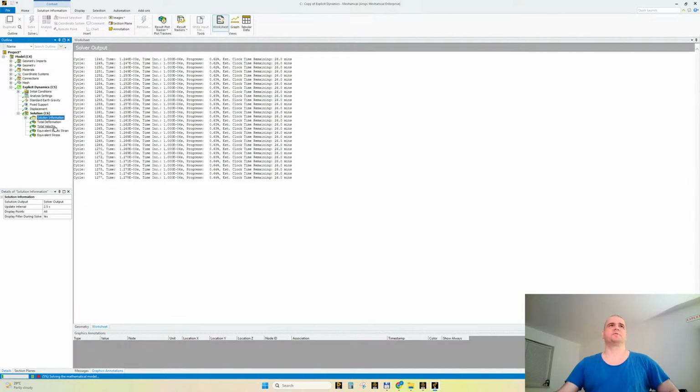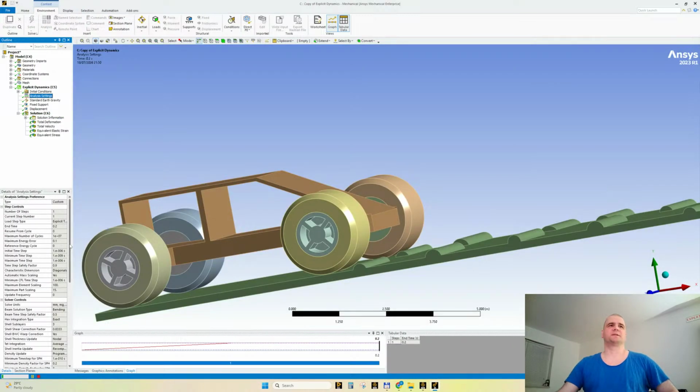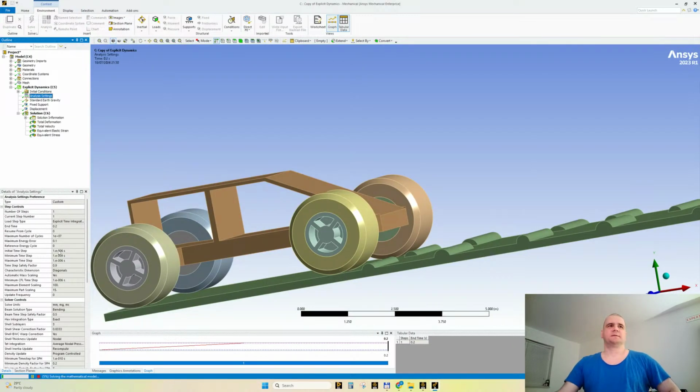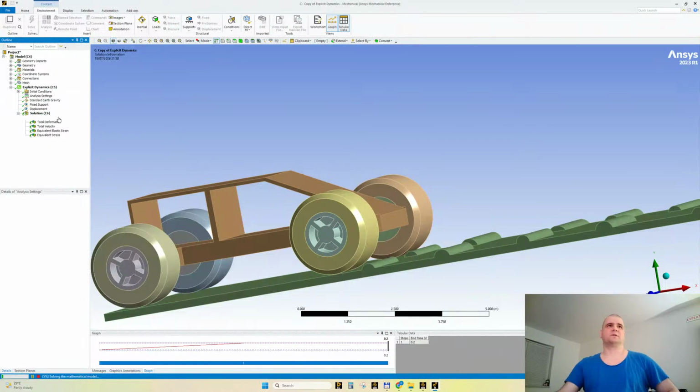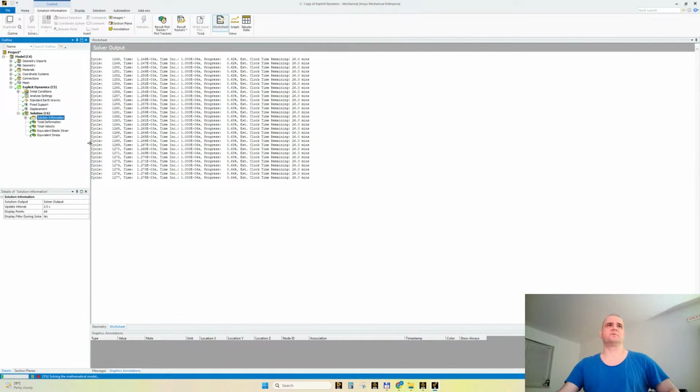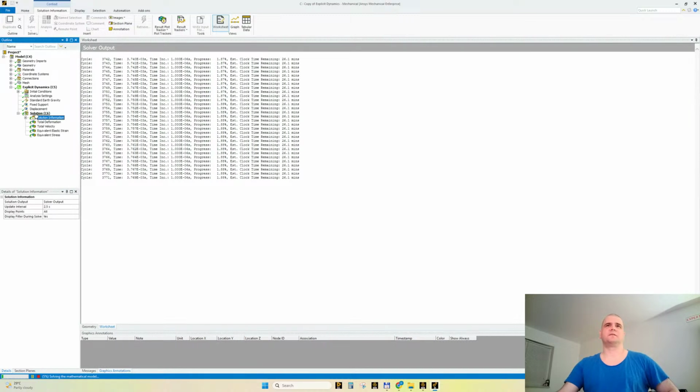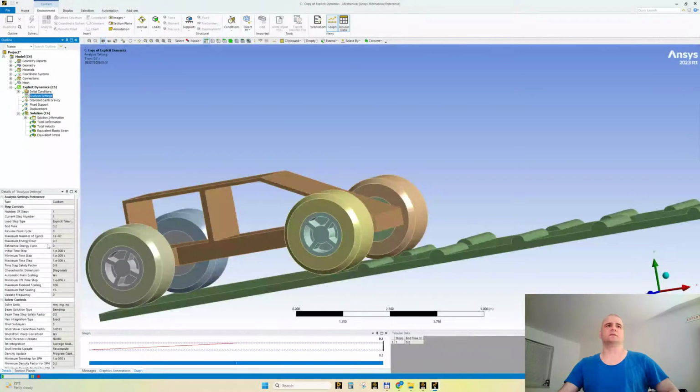For the people who just joined, remember about this. Here, look here. I'm talking especially about mass scaling. Otherwise, you will solve the simulation in a few good hours, maybe 5, 10, 20 hours. Just take this into account.